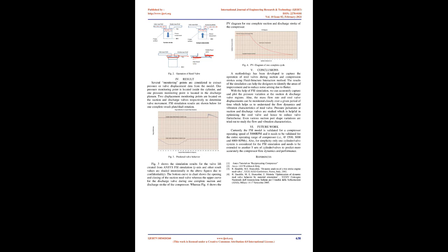Pressure pulsations at suction and discharge valves are studied, which is helpful in optimizing the reed valve and hence to reduce valve flutter/noise. Even various suction port shape variations are tried out to study the flow and vibration characteristics. Future work.